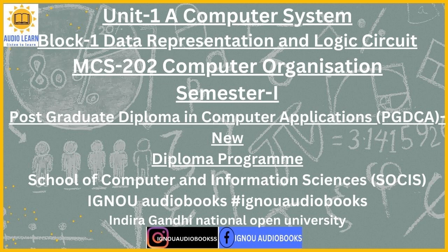A continuous pulse sequence is generated by a system clock over a set period of time. This sequence of steps, identified as T0, T1, T2, where T0 is less than or equal to T1, which is less than or equal to T2, is used to perform a specific command by enabling control signals in a specific order. The details on various types of control units and their operation are discussed in Block 3 of this course.